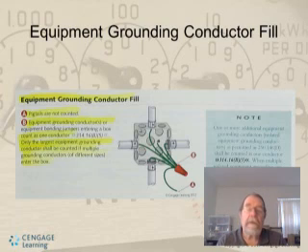Hold on a second. Okay, I stand corrected. The pigtail, which is option A, is not counted, but the largest conductor in that bundle is what's counted as one conductor. All the other ones are not. So if you have 14 gauge coming in there, and then you got one 12 gauge, that 12 gauge conductor is the one that's counted. So essentially, that's how that one's counted.